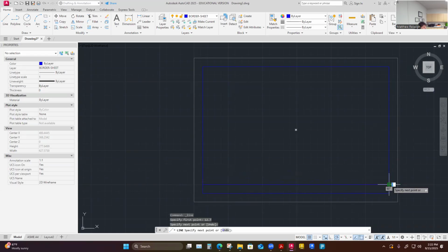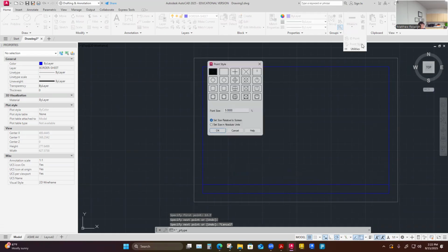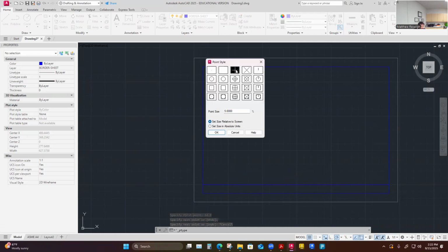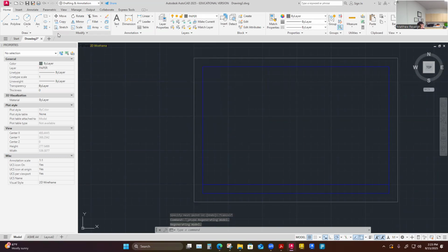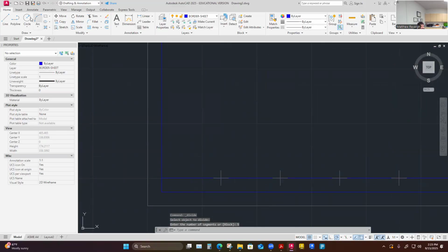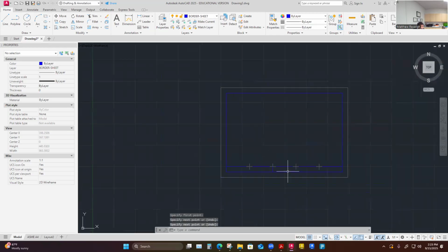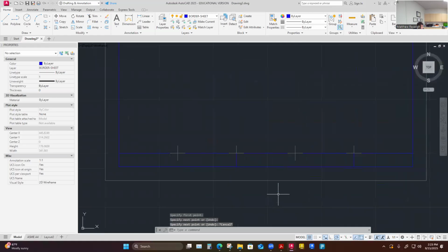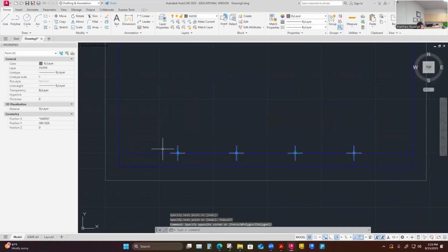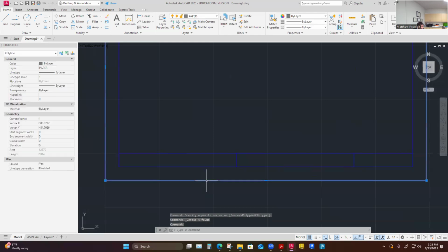12.7, enter, crossed. I probably need to set my point style in here too. It'll just be, by default, the small one. So I'll pick that one and say okay. And maybe I'll put these on the paper layer when I divide that by 5, and just draw a couple. I'll divide this up the same way. 2/5 of it that way, 1/5 of it that way. Repeat my line command. Looks pretty good. Erase these. Erase this.